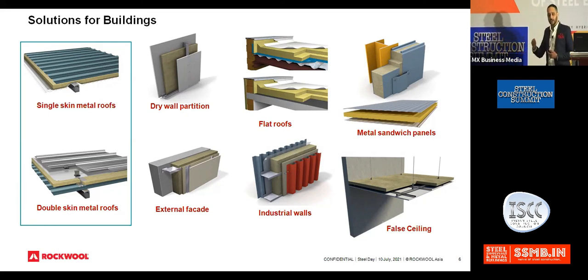Then we have a special insulation solution for dry walls, because probably you need fire performance and acoustic rather than thermal for a dry wall. So we have a special insulation for that as well. And the fourth category, as I mentioned earlier, we have insulation solutions for prefabricated or metal sandwich panels as well. Because in that, the compressive strength, the shear strength, and the tensile strength of the insulation material is very, very critical. So that's the material that we are manufacturing for a sandwich panel. So just keeping this slide for you all to have a look regarding the solutions that we are offering.